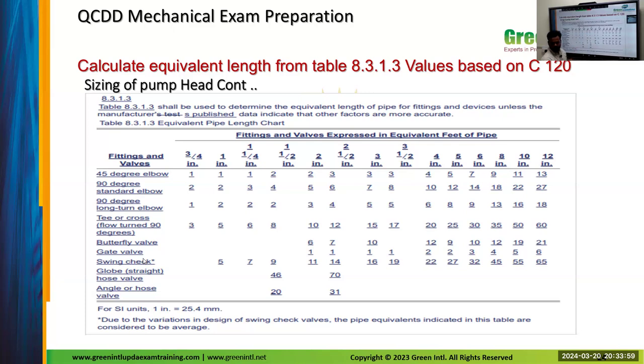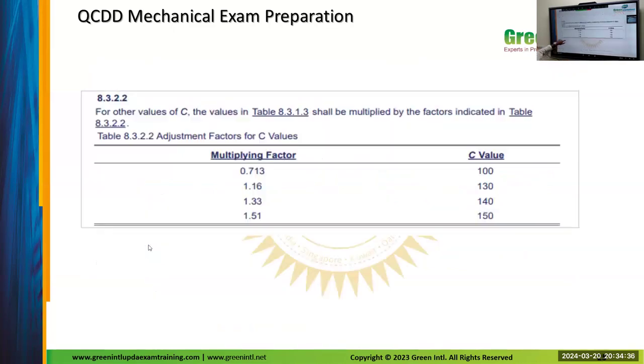So we will calculate for this much total length, there will be a pressure drop. Correct? So for elbow, T, butterfly valve, gate valve, we cannot measure the length. Instead, for each inch, what will be the equivalent length? From this equivalent length, there is a formula for finding pressure drop. We have to multiply with those factors.